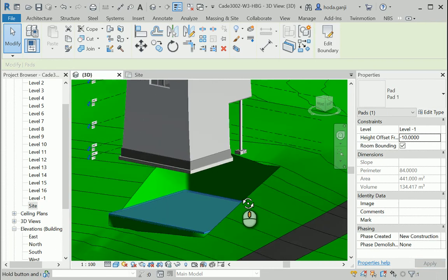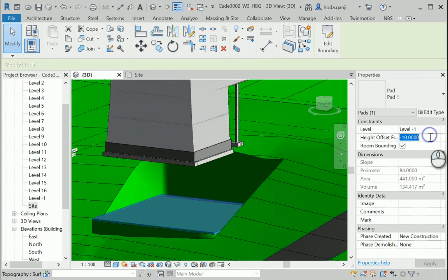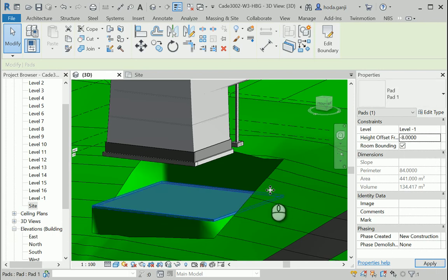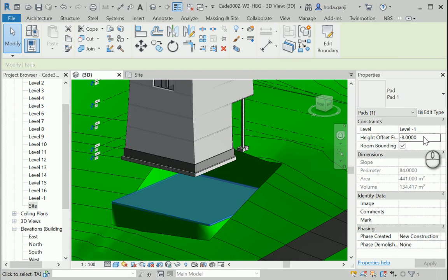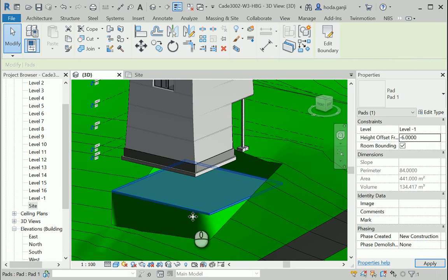It's a little bit better, even -8 or something. So maybe a better idea is to first find the best location for the building pad, so it has the best ratio between the volume that you need to fill and the volume that you need to cut, and then adjust the whole levels. That would have been better.